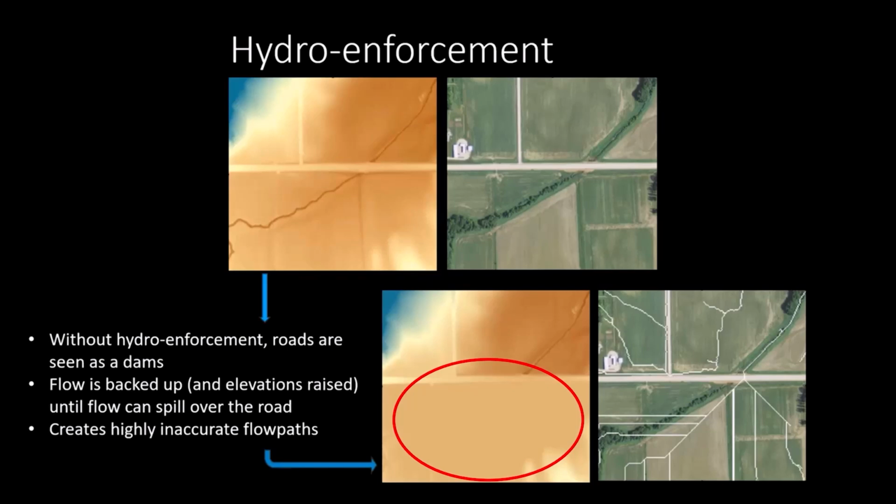So it's extremely important to make cuts where you know they are and you can see them in your imagery or hillshade, because you want your flow paths to fall within the actual channel and not just spilling all over the place, like you can see in that lower image on the right with the white lines. We want accuracy, so we can suggest good results to our watershed planners.